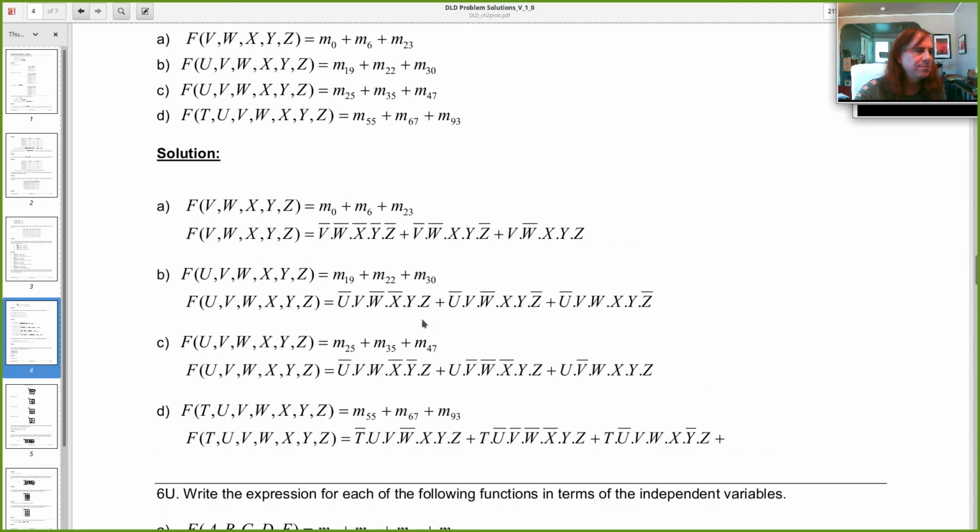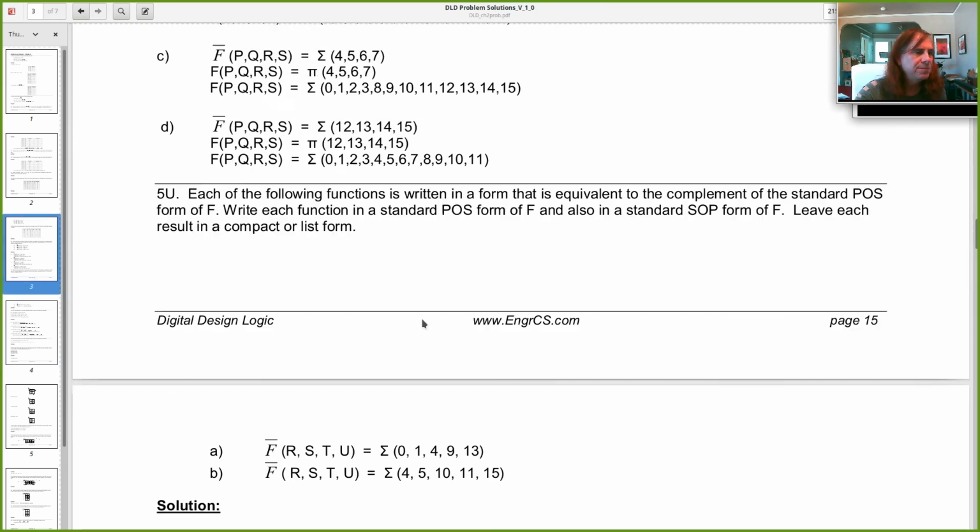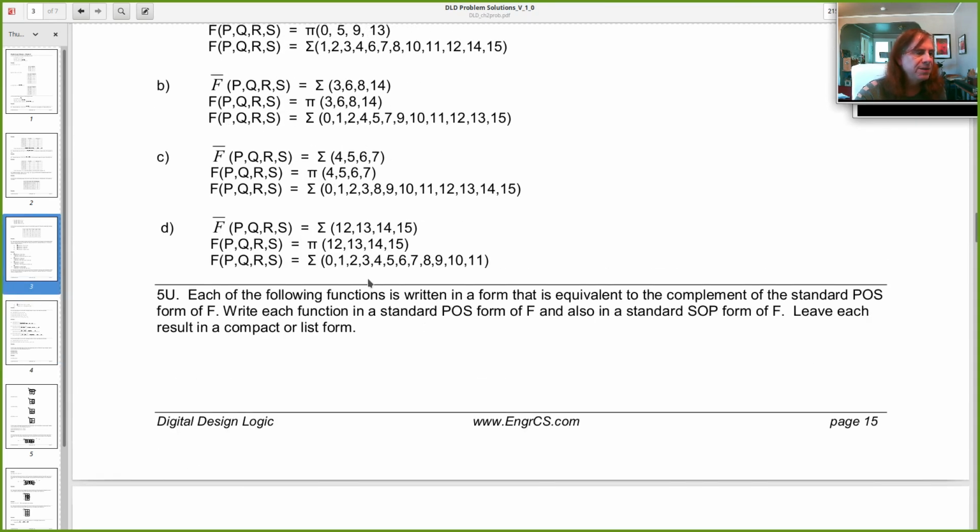What is the pi and summation at the front of the outputs for again? So this is a sum of products, sum of min terms 0, 1, 2, 3, 10, 11, and so on. The summation says it's the sum. The pi is a product, so this is a product of sums, which means each of these is a max term. So this is the product of max terms 12, 13, 14, and 15. Product just meaning and, sum meaning or.